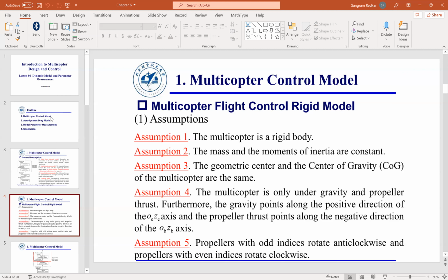So that is something that you have to take into account. In other words, the body frame of the aircraft may or may not be aligned with Earth center, Earth fixed, but if you want to resolve the gravity, you would have to use those transformations that we talked about to find the component of gravity on the aircraft. I'll give you a very simple example.